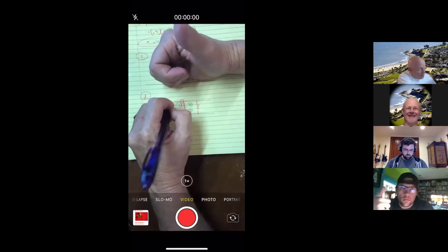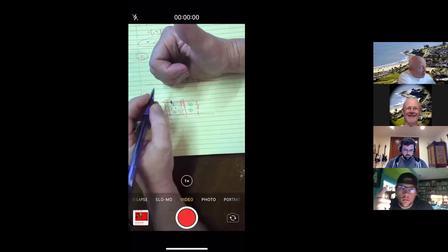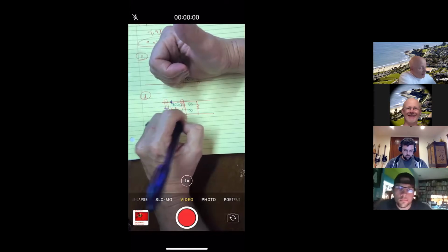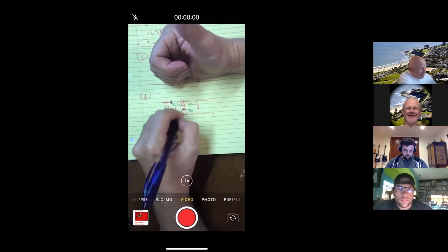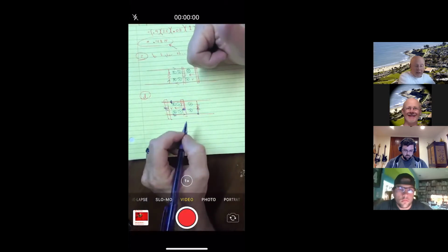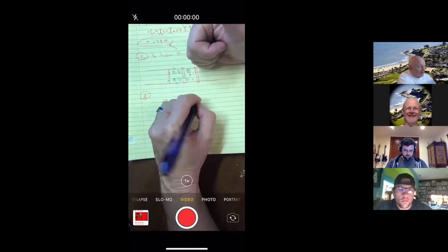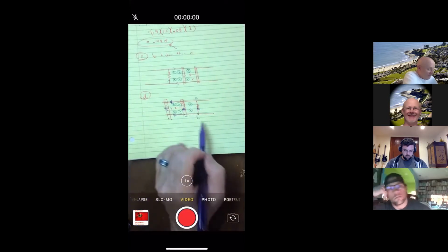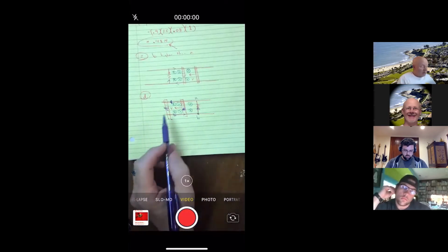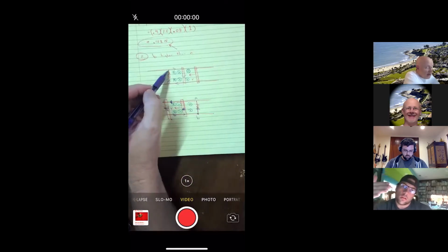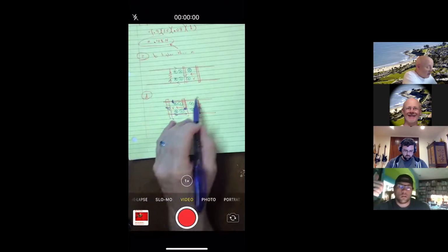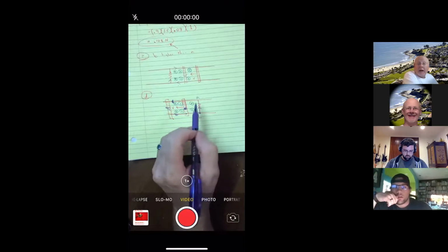Now, if I'm not careful, I will say, well, that's opposite. It was going clockwise, now it's going counterclockwise. Well, okay, but that is still, at this resistor, from the bottom of the resistor up. That is still from point B to point A. And so I would say in the resistor, it hasn't changed direction. It went from bottom to top before we got to the resistor. Then after it passed the resistor, it's still going from bottom to top.